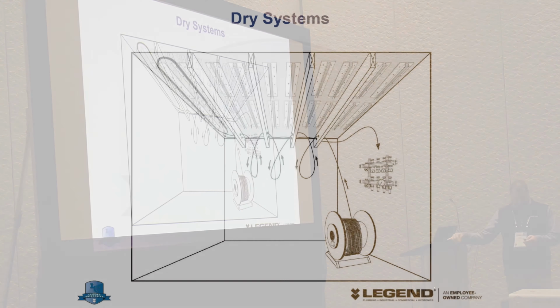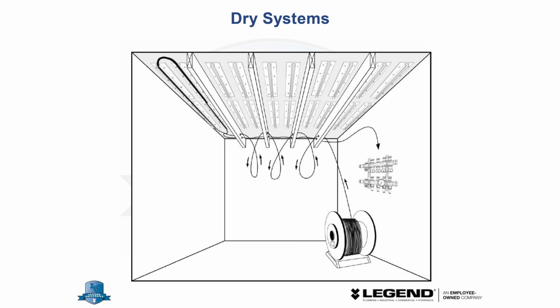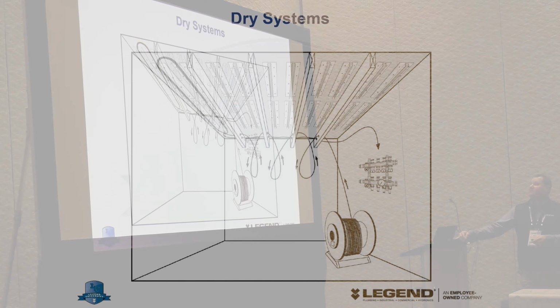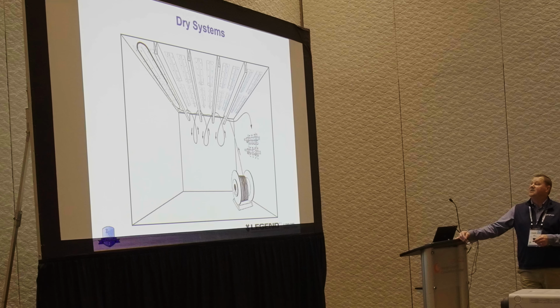And when you're doing heat transfer plates, the technique for installing them is, this is a simple one zone. I'm going to go ahead and I'm going to run all my heat transfer plates. I'm going to install them. And these heat transfer plates have holes pre-drilled in them. We're not shooting them with nails. And if it's got 10 holes that are pre-drilled in there, you need to put 10 screws in there.